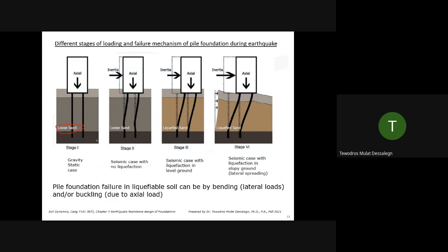Or even piles which are in shallow depths. Let's say you may have rock and you can put your pile foundation socketed to the rock. So even if this soil liquefies, you may assume, hey, I may not have any issue. But still, you may have. In loose sand, you have inertial forces. There are two kinds of forces. We'll see it in detail later, but you have kinematic interaction and inertial interaction.